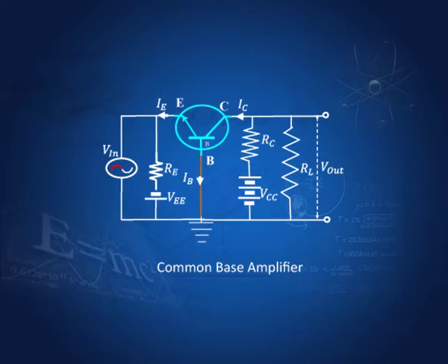So, what do we do? If you just put them together, the power transfer is not very efficient. However, if we put some such device in between, with the input connected here and the output connected here, the input of the device from which power is to be transferred to the output to which the power is transferred. If in between we put this common base amplifier, then the transfer of power from the active device to another device is much more efficient, because there is impedance matching.